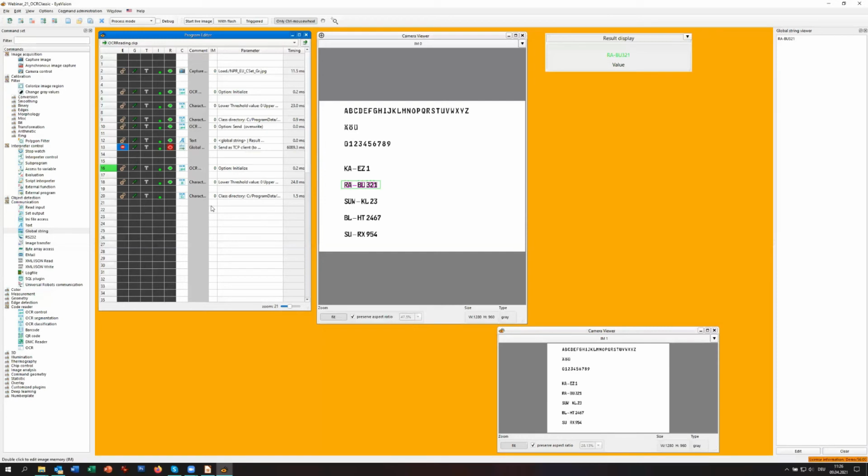I think maybe a short word only on how to program the ivision software. I think you saw it anyway. I made some examples with it. You simply select the tools from the left side and drag them into the program editor to the command column and release it. Then you do the configuration of each tool, and then the tool is working. If you want to prevent the tool from being executed, you have this execution column. Here you have 4 or more options.